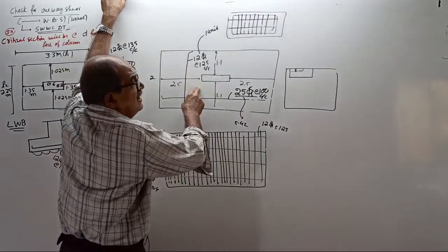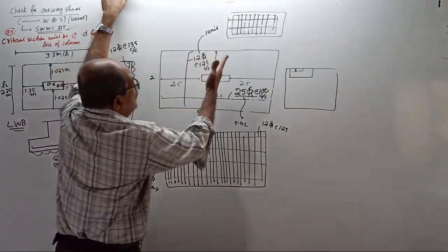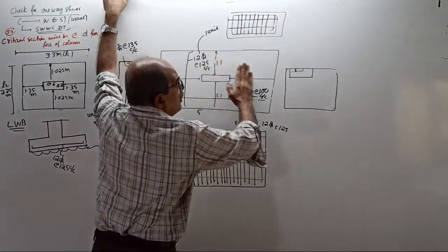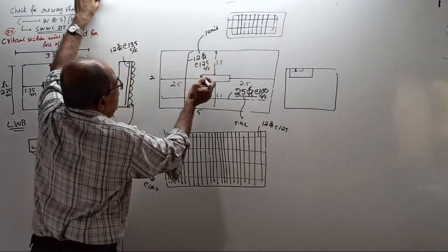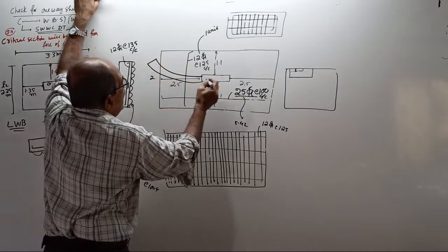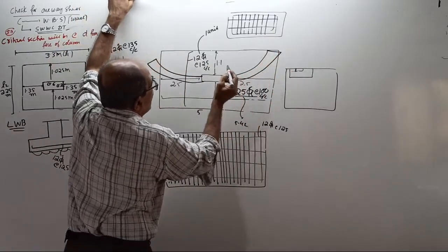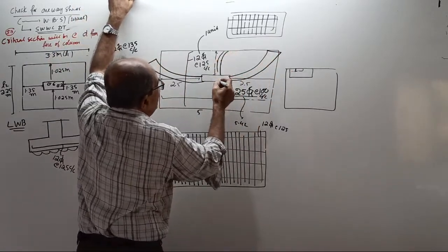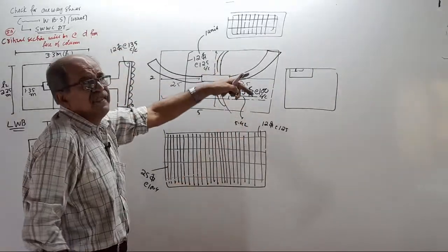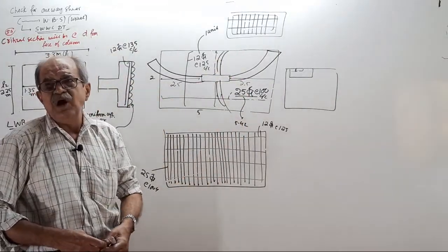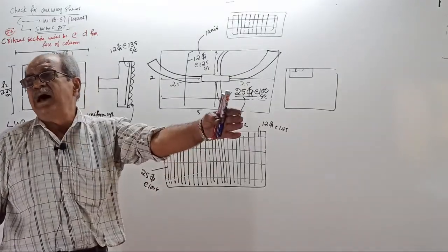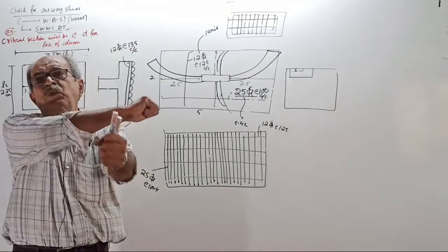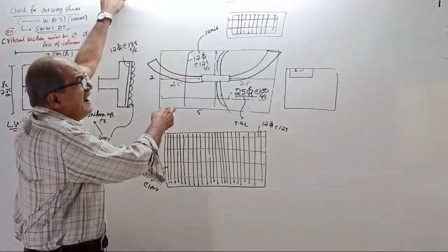In footing, there is no ratio. Here bending depends on the projection. Heavy projection here, this will bend very heavily. Very heavy bending, very heavy shear. This will bend lightly. Therefore, major mistake. This is because of what the bar bender thought. He always knows that for footing, along the longer span, they usually provide equal steel. This is a rare case.